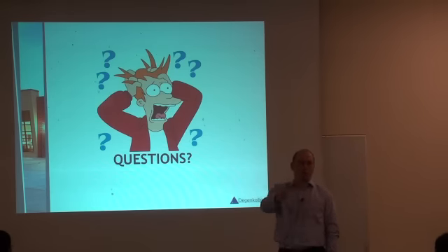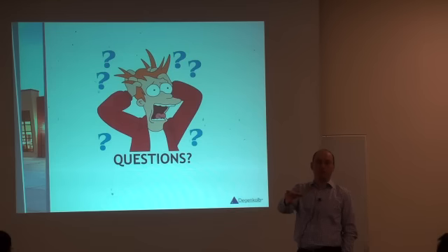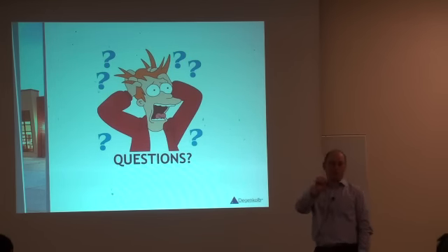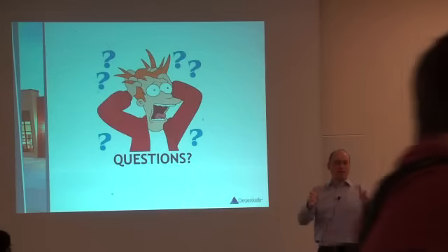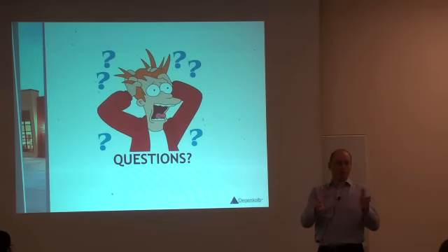You can also get the same thing within the same software, just doing some sensitivity analysis. So if I modify my strength by 10% or by 5%, or if I have asymmetric strength or stiffness, how does that affect my results? If that affects my results significantly, that's also telling me that I'm missing something.